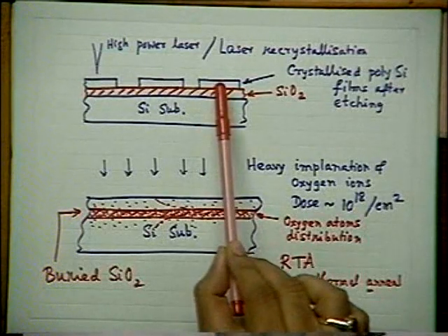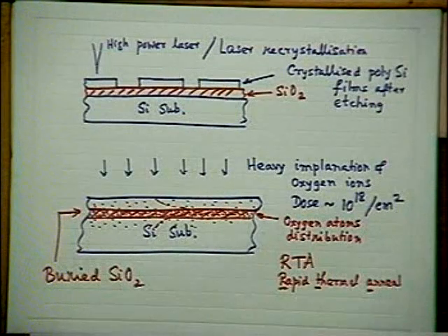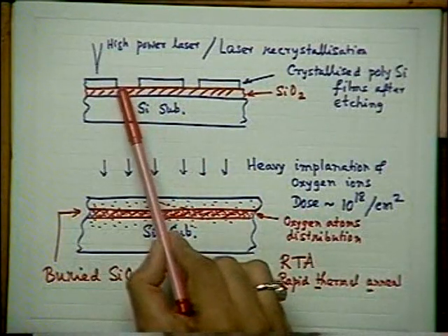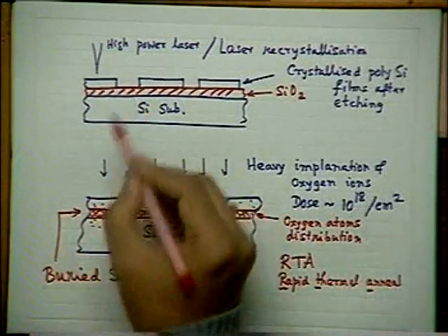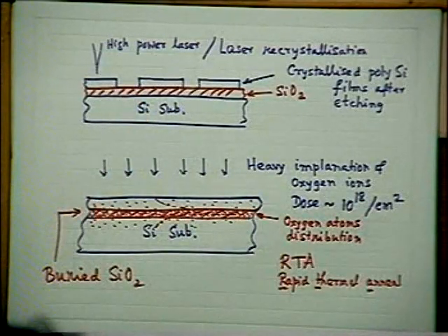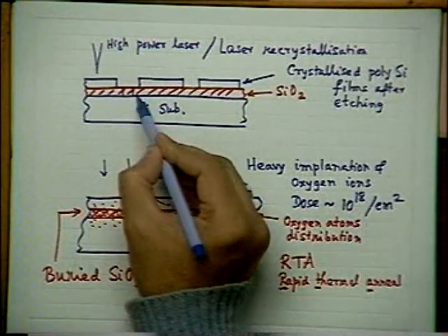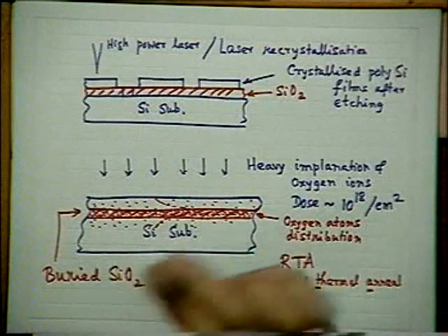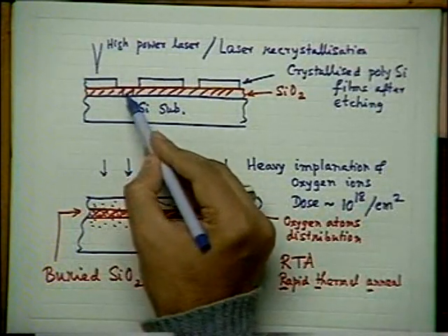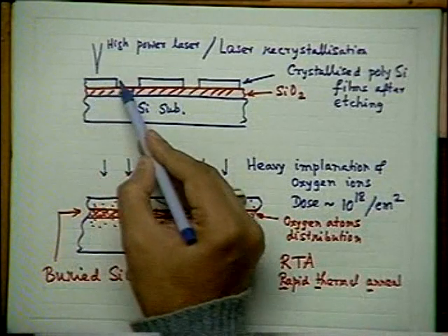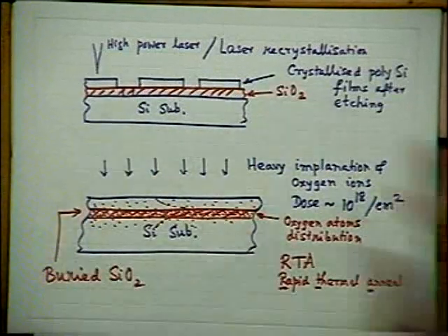To get a very excellent quality silicon film on oxide here is difficult. Some people have tried etching the oxide. Suppose here, if you etch the oxide, remove the oxide from here. I think you understand my limitation now, I cannot wipe it off as on the blackboard. So I just remove the oxide from here and then grow this polysilicon film and then do the laser sweeping.